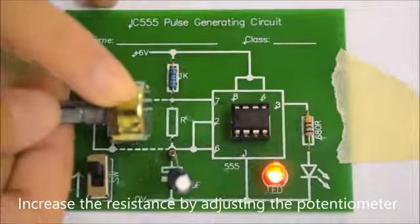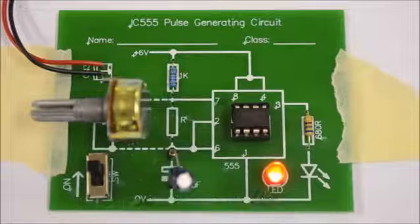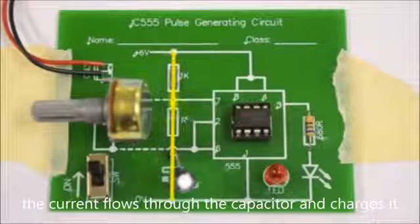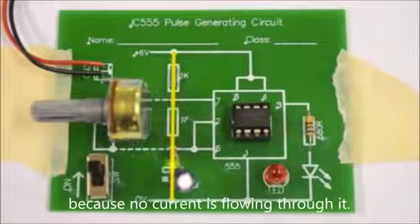Increase the resistance by adjusting the potentiometer. See that the LED starts to blink. Let's examine how the blinking occurs. When the switch is on, the current flows through the capacitor and charges it. When this happens, the LED does not light up because no current is flowing through it.